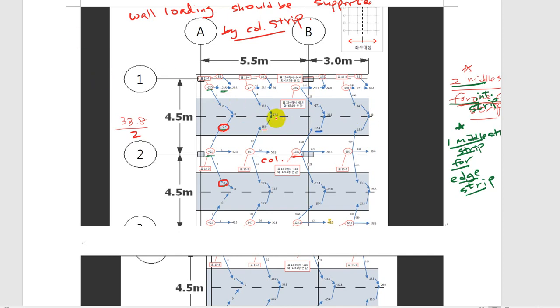Okay, so the design moment here, as a matter of fact, is 37.6 for positive and 0 for negative at the exterior edge of the exterior span, and in the interior span we have a minus 32.5 and another positive 28, and this repeats for the other side of the slab, because these slabs are symmetric.